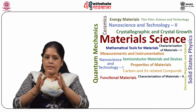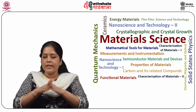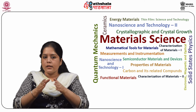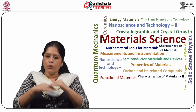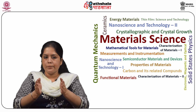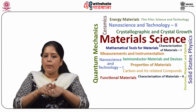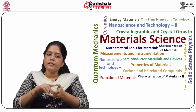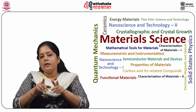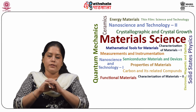Second type is the continuous oscillation method. Now here the sample is subjected to a continuous sinusoidally modulated heat source. The basic idea is that if the source frequency is low enough to consider the sample homogeneously heated, then the component of the current originated from pyroelectricity is 90° out of phase with that of the thermal wave. This allows the accurate measurement of the pyroelectric effect.